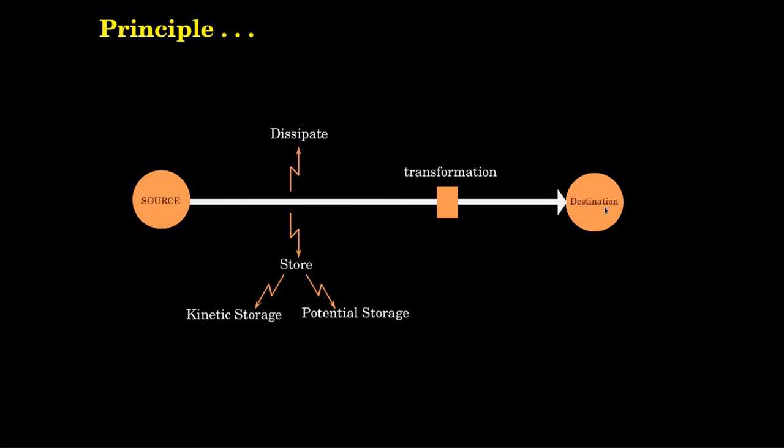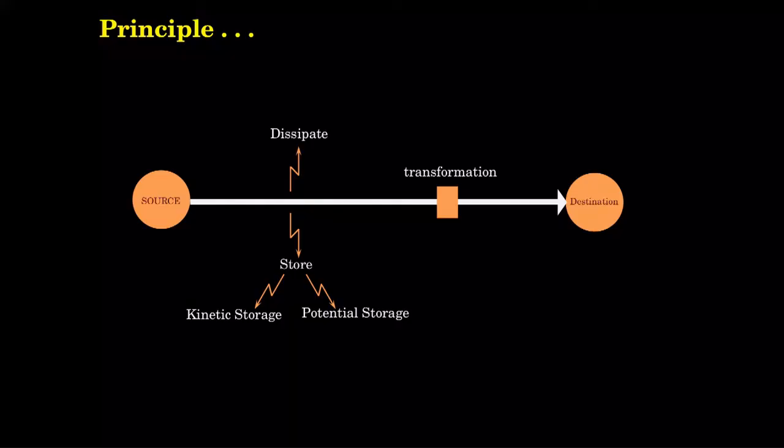So, this is actually what we will be trying to model. When energy is flowing, when power is flowing, we will see where it can dissipate and where it can store, or can it store at all, and this in fact will give you the clue for putting in the variables. This along with causality. The moment I know that I am having an a-causal thing, I know it cannot be, and therefore, you will start adding in non-idealities like a capacitance across a junction, or capacitance across a typical textbook attenuator of resistance by resistance which cannot exist. These kinds of things you will start adding, knowing that this is how the energy can flow.